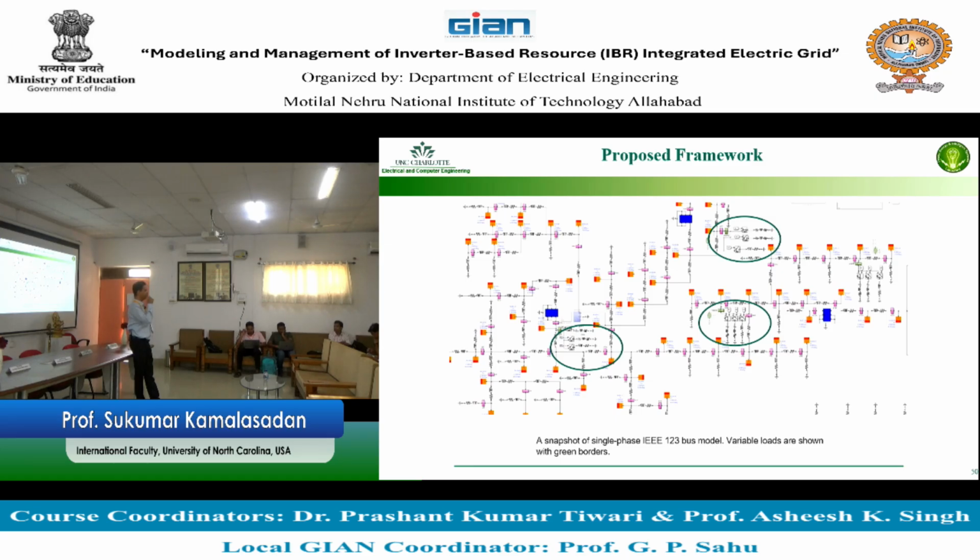What will the reactive control do? What's the difference between reactive control, power control, and voltage control? You understood? What is the voltage control? It is just to maintain the voltage at the point that you control. Reactive power control is to push the reactive power to the system, not necessarily maintaining the voltage at that point. So that's the difference between reactive power and voltage control.